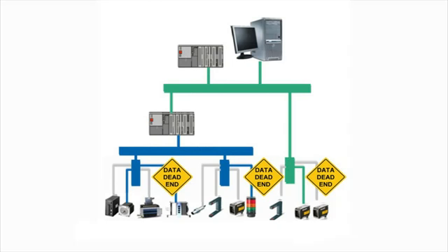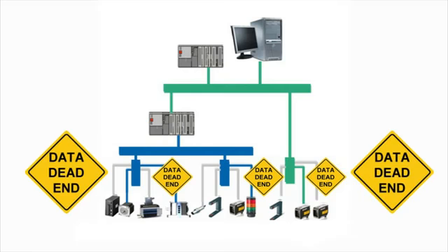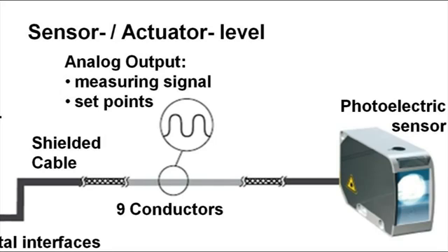Field bus communication covers vertical integration right up to total plant control, and it ends at the field level hub. It unfortunately does not include the link to the lowest level, the sensor-actuator level. Modern-day sensors and actuators equipped with multiple functions and intelligence usually require configuration and also can supply the controls with process data, digital signals or analog measured values, and diagnostic information.